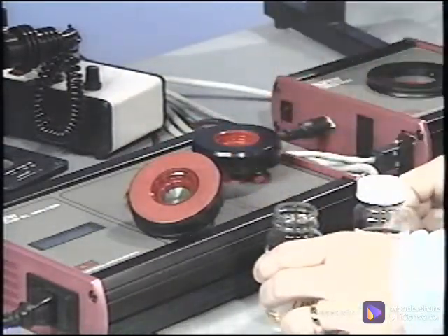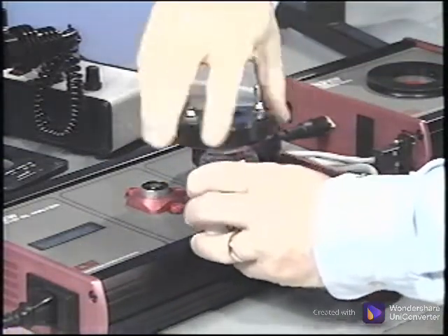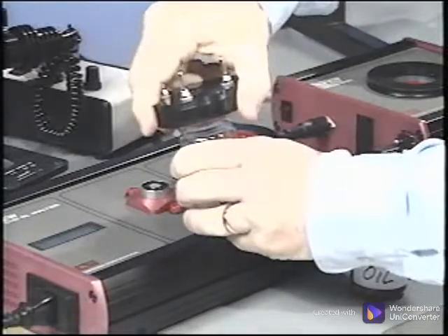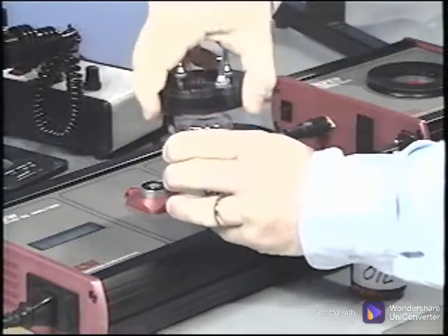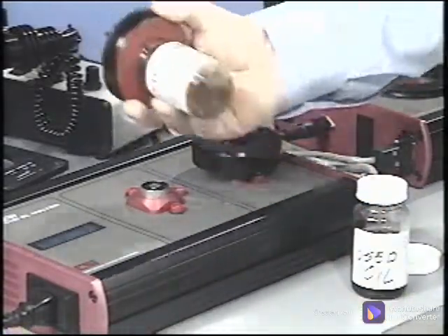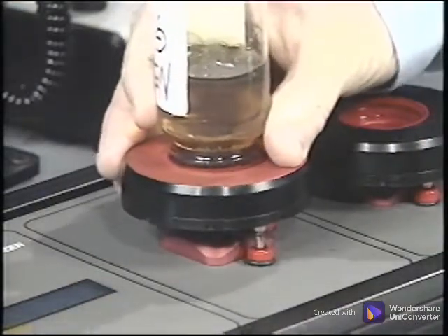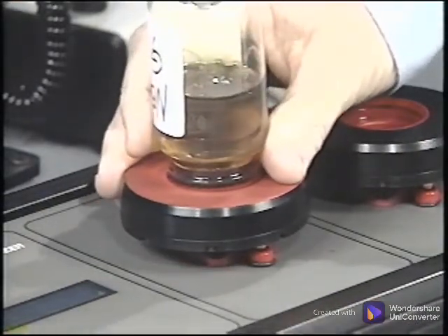A full test must be run on the new clean oil as well as the used oil because, unfortunately, new oil samples sometimes have dirt and water, and must be inspected periodically to ensure harmful contaminants are not being introduced into the system. When the new lube is tested, it is recorded in a database for easy retrieval and comparison with future samples.